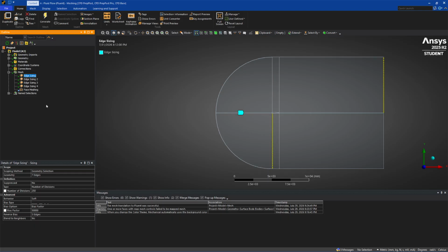So we go ahead and get that done, and then we work on our next area. So this is just this area right here. Similarly, we have our meshes being condensed towards the airfoil, so that this area around the airfoil is our most meshed area. Then we're working on these vertical points. These are all just hard divisions, not biased. And this just gives us the area over the airfoil. This front bit, same thing, just giving us some points of interest at the front so we can measure where the air is coming in from and how it's hitting the tip of the airfoil.